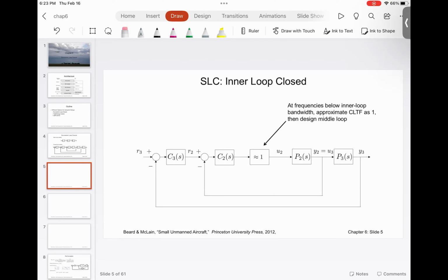The deflection of those control surfaces will be done with some actuators. Now the actuators need to be moved. The pilot is not going to move the actuators by hand, but is going to actuate a lever. This motion of the lever needs to be amplified by a gain that results in the motion of that huge actuator. Think about power steering. You move the steering a little bit in one direction, but your wheels turn a lot.